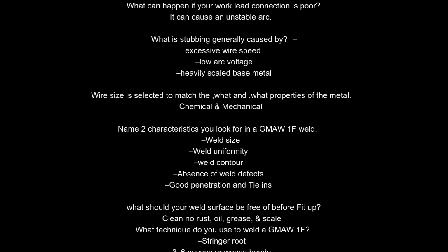Name 2 characteristics you look for in a GMAW 1F weld. Weld size, weld uniformity, weld contour, absence of weld defects, good penetration and tie-ins. What should your weld surface be free of before fit up? Clean, no rust, oil, grease, scale.